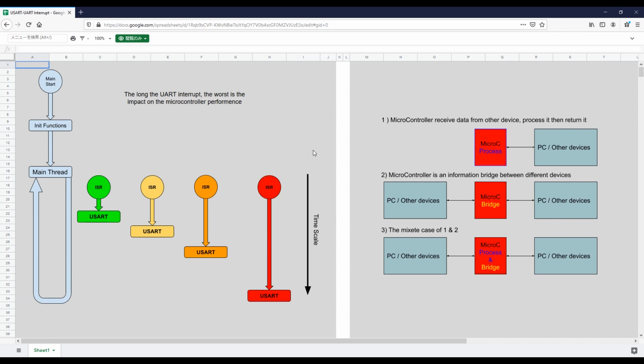So the one rule in the code that we will be writing is to put as little code as possible in the ISR and let the main thread manage it later on. The longer your ISR is, the more you affect your real-time system, so you should be quite careful about this. This is in general, and we are going to apply it in our next example.